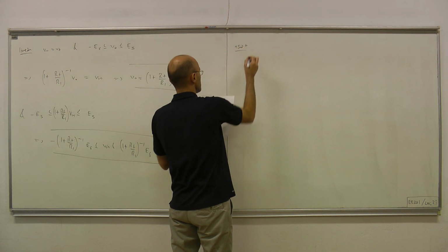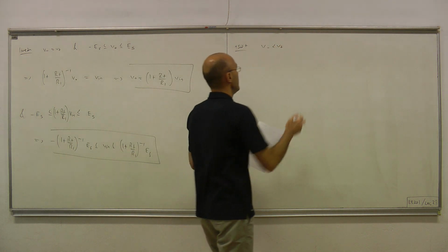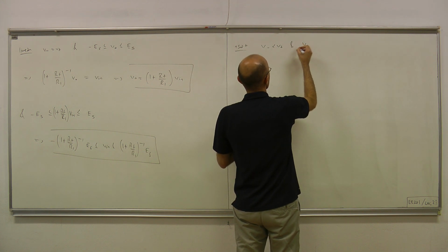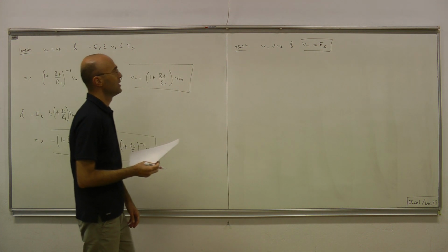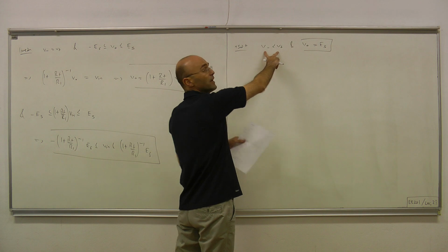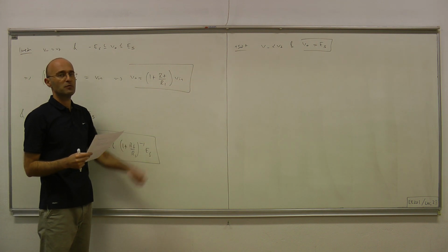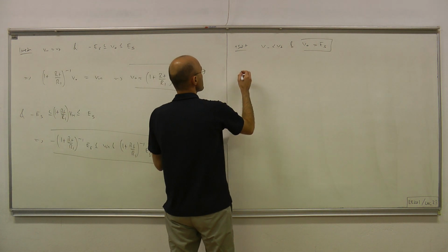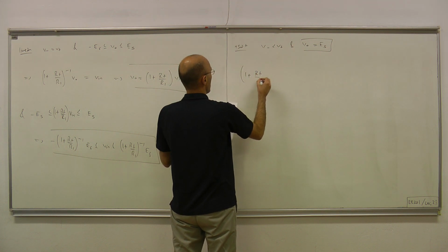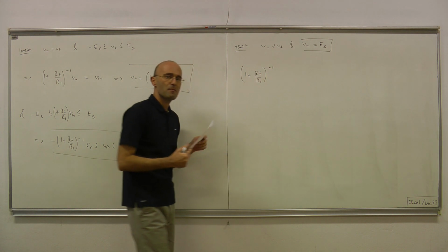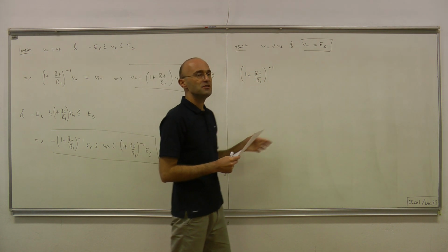Okay, positive saturation region: V minus smaller than V plus, and V out is fixed at positive saturation voltage. To translate this condition into a condition in terms of input voltage, we write V minus equals (1 plus RF over R1) inverse times V out, that's equation 1, and V out in the positive saturation region is ES.